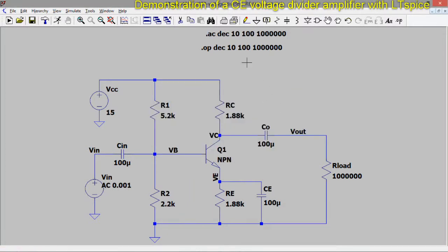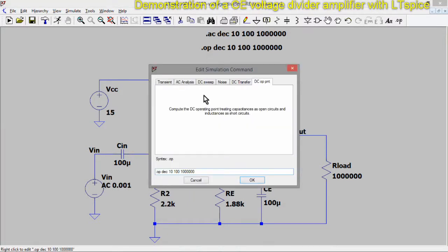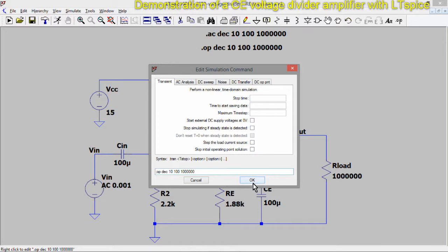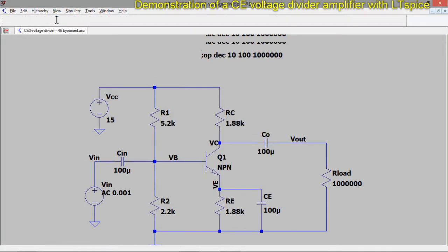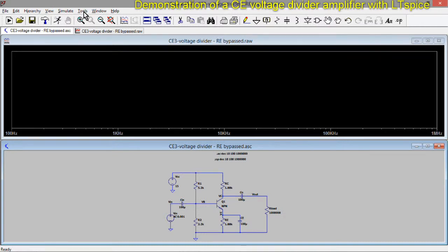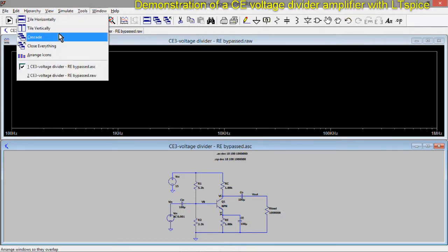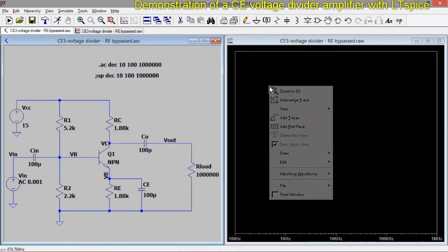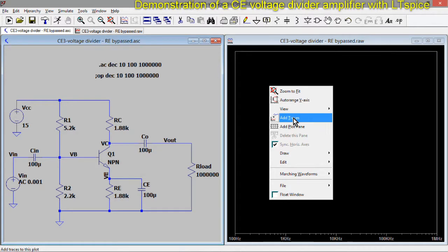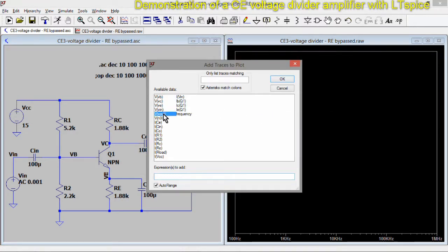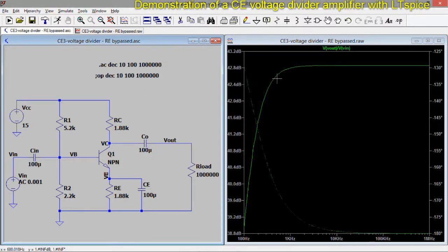Let's now run the AC analysis. I've run it in frequency from 100 Hertz to 1 megahertz, which is the low frequency regime, as we called it. I will plot here now. First thing we want to check is the voltage amplification, for example. So I will plot V out over V in, as is defined on the diagram.